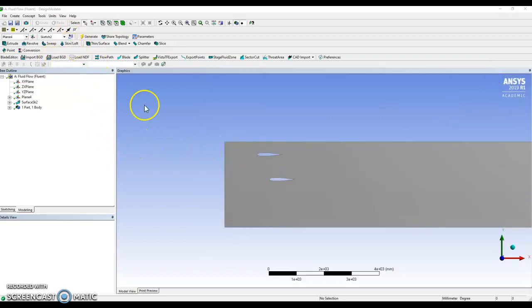Once the nodes have been imported into Ansys, you can then use the Concepts tool to create a 3D curve. And you would then go onto a 3D curve, and you would select Draw from Nodes, and you would join up all of the nodes from the top tail all the way around to the bottom tail node, and then you would accept, and then you would draw a line between the two nodes to seal off the aerofoil and make it a complete shape instead of leaving a gap, as it would if you were just using a 3D curve.